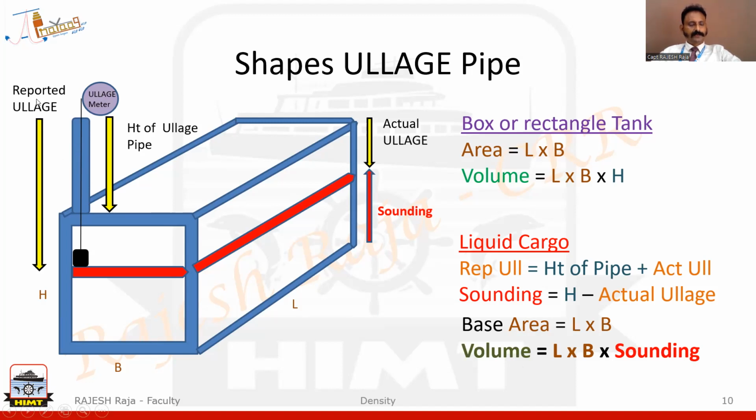So please remember, reported ullage is height of ullage pipe plus actual ullage. I'm not interested in height of ullage pipe. That is why I remove it. I calculate actual ullage. And from actual ullage, I'll find the sounding. So this is how you go about in your rectangular tank calculations, or any other calculations also.